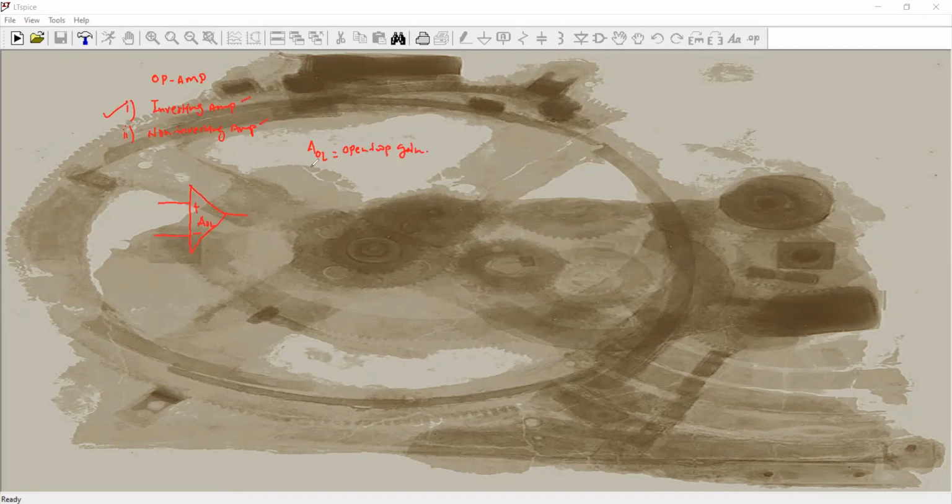of an amplifier. So what you do here, you basically apply an external input signal, that is Vin, at some frequency to this inverting terminal through a resistor called R1, let's say. And then here you have an output, and from the output you apply negative feedback.